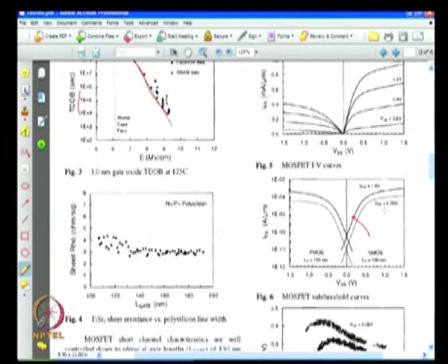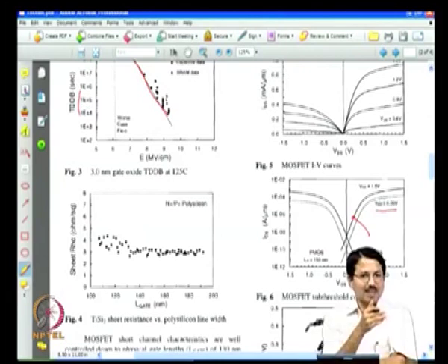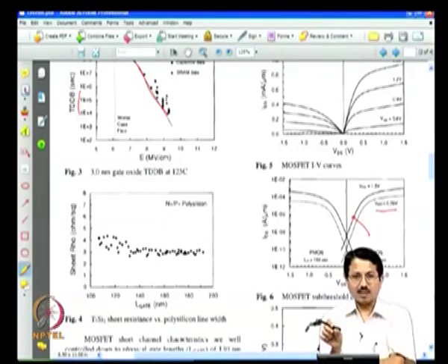And again notice that depending on whether you have 0.05 volt here or 1.5 volt here, you will have different characteristics. That is essentially due to the DIBL effect, drain induced barrier lowering. If you have larger drain voltage for the same gate voltage, you get larger current, because your drain electric field will influence the injection at the source side, especially in these nanometric dimension transistors. Okay.